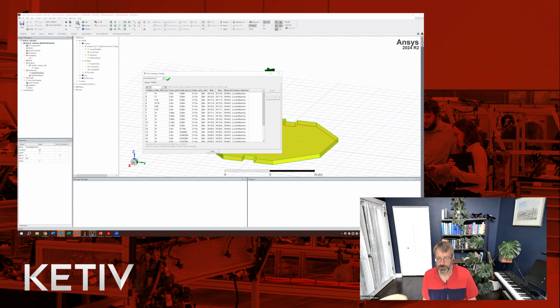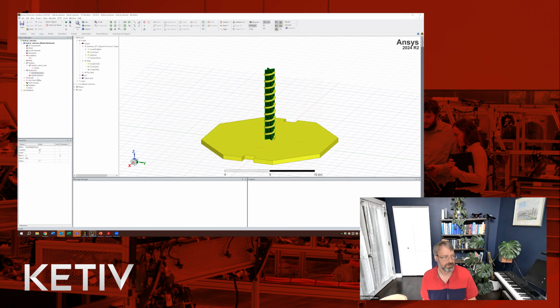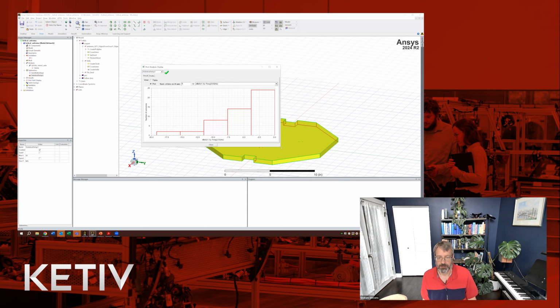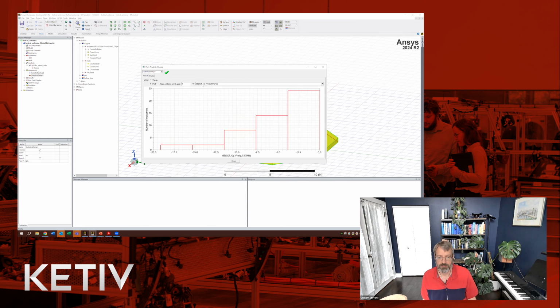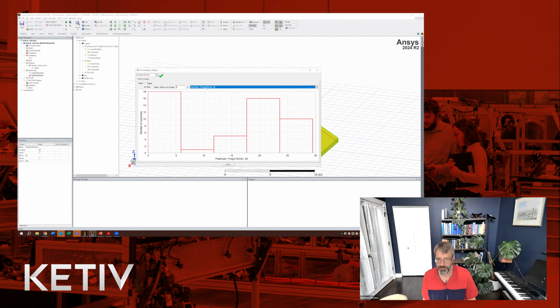And so this is the output for this kind of analysis. And this profile shows you how many models it ran and what my input variables were for each of those runs. So that's on the sensitivity side, what the results look like. And on the statistical setup, we again right-click here and view analysis result. We can now look at S11 or the peak gain. I just did like 50 runs instead of thousands, just to make it a shorter runtime, but we can see the number of outcomes distributed here and what our output S11 is and our peak gain.